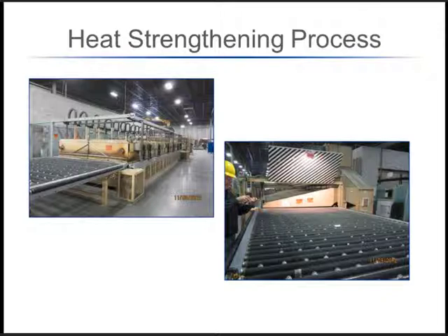And then at the end, once it's done, it actually comes out on the rollers, and you can see that diagonal board there, which is called a zebra board. And they use that just as an unofficial way to see how much roller wave distortion might be in that glass. And we can save roller wave distortion for an entire webinar another day.